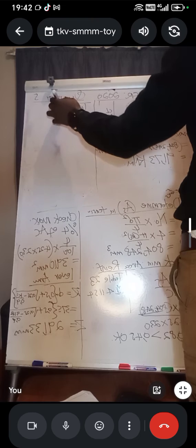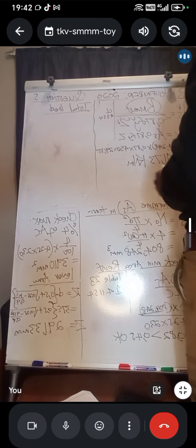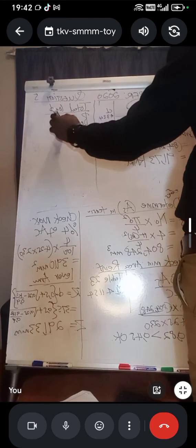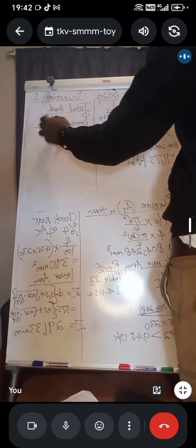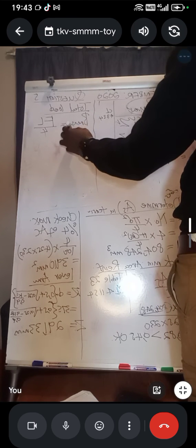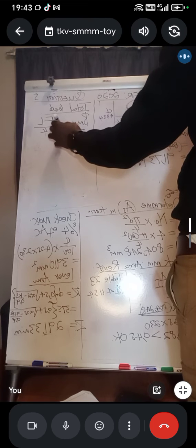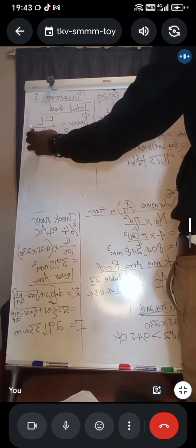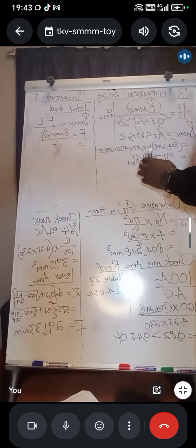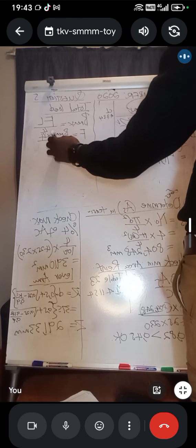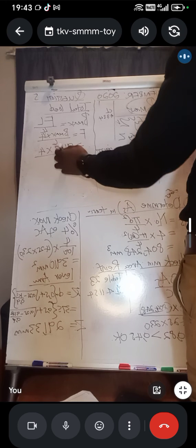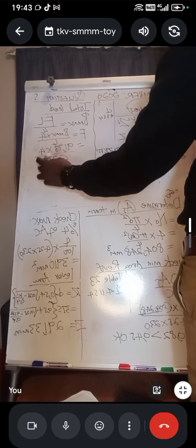How do you calculate the total load? I've already given you the answer, whereby Bmax equals FL divided by 4. You cross multiply, you're looking for the point load, which is going to be FL. It's going to be Bmax multiplied by 4 divided by the span. So what is the Bmax? We said we are getting 91.73 by 4 divided by what was it? Was 6.35, ne? The span. Yeah, 6.35. Yes, that's how it is.